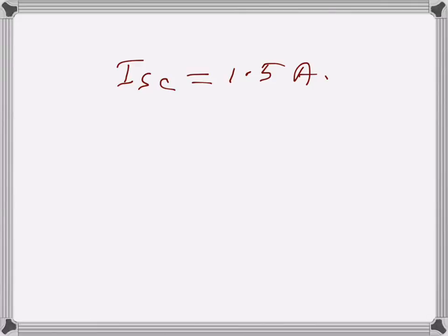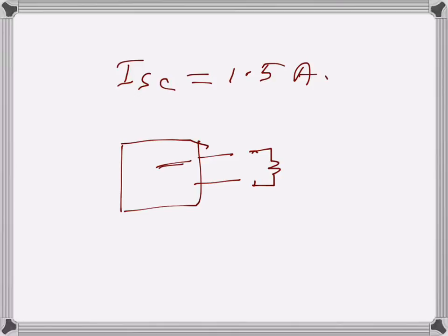The open circuit voltage is the maximum voltage that the network can offer to any load when the load is connected. But this is before the load is connected, because when the load is connected there will be flow of current and there will be some internal drop. So without that, it's the maximum possible voltage that the network can offer to a load.